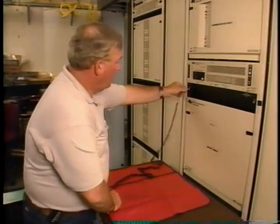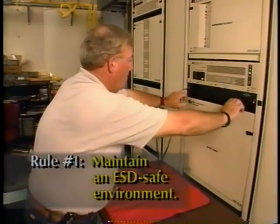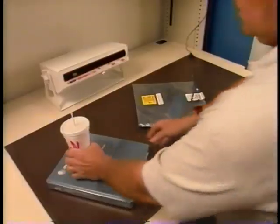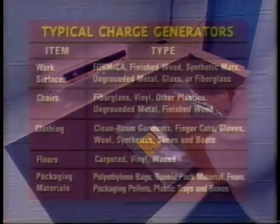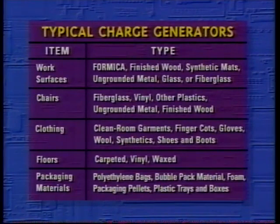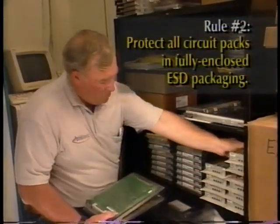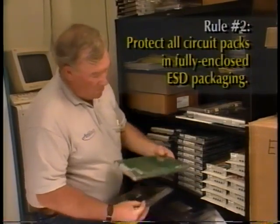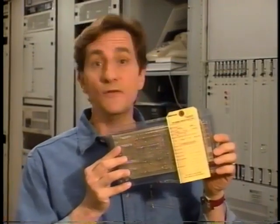There are 4 general rules to keep in mind when handling circuit packs and other ESD-sensitive devices. Rule number 1, always maintain an ESD-safe environment when handling circuit packs and tending systems. All non-essential charge-generating materials and devices should be kept at least 3 feet away. This table lists typical charge generators including work surfaces, chairs, clothing, and floors. Rule number 2, protect all circuit packs in fully enclosed ESD protective packaging while stored or in transport. This includes circuit packs you may believe are defective.